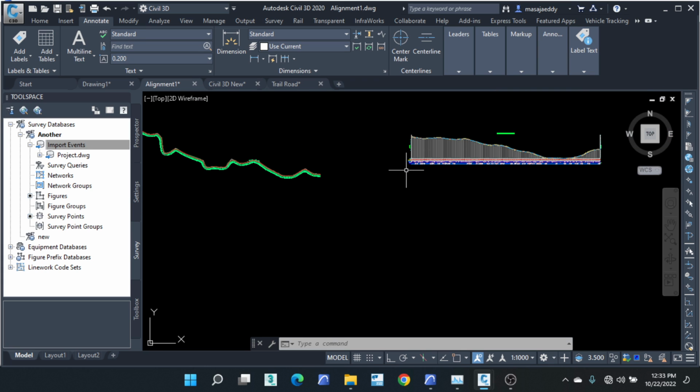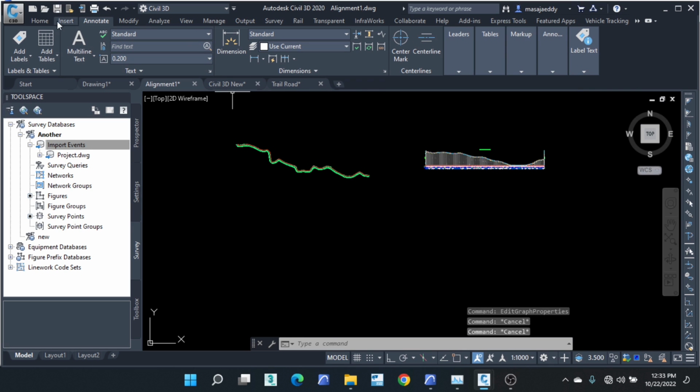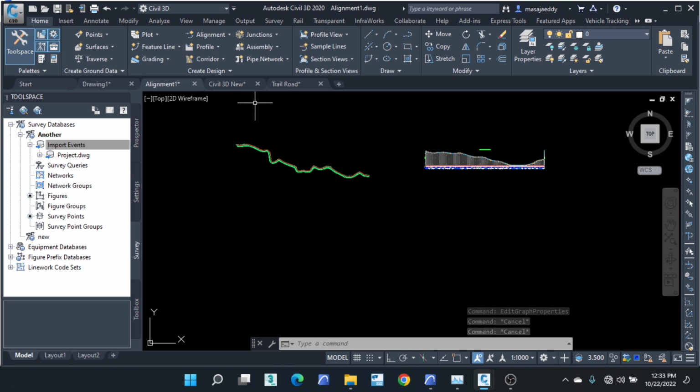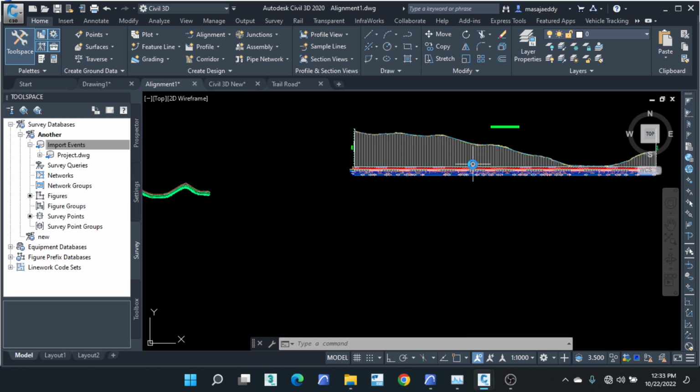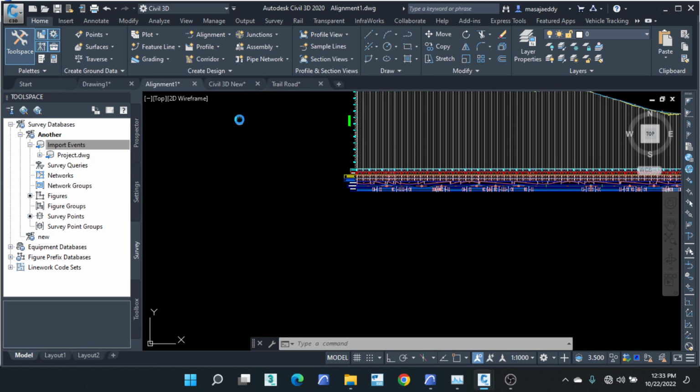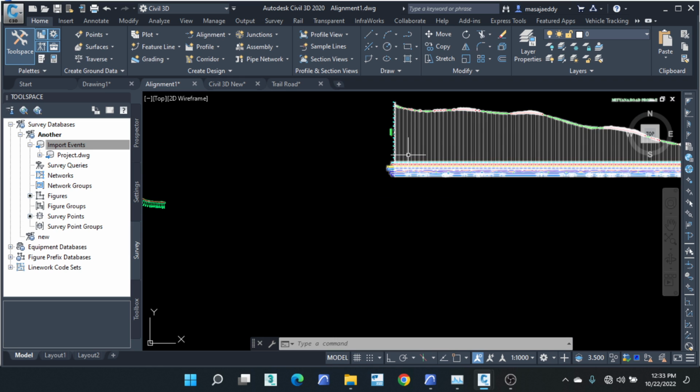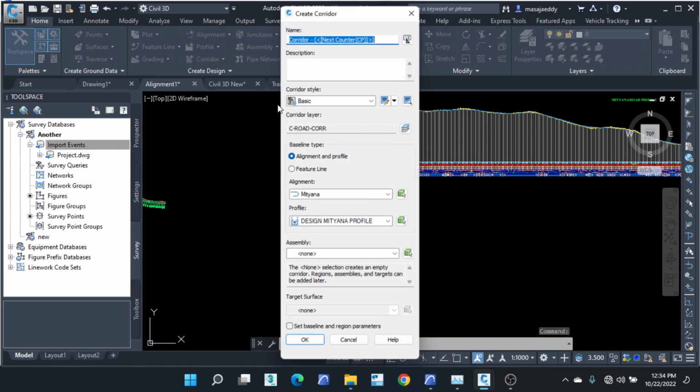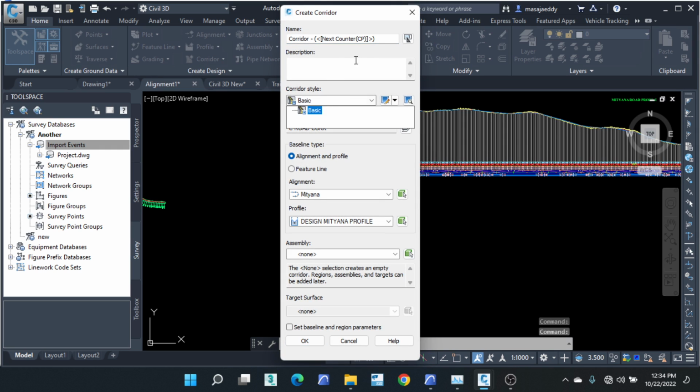So now we are going to introduce how to design our corridor, right? So once you come to your corridor, by the way, I hope everyone has added these bands. If you have added those bands, it's okay. You edit those during your free time. So you're going to come to corridor. You create a new corridor. As you can see, these are the variables they need.